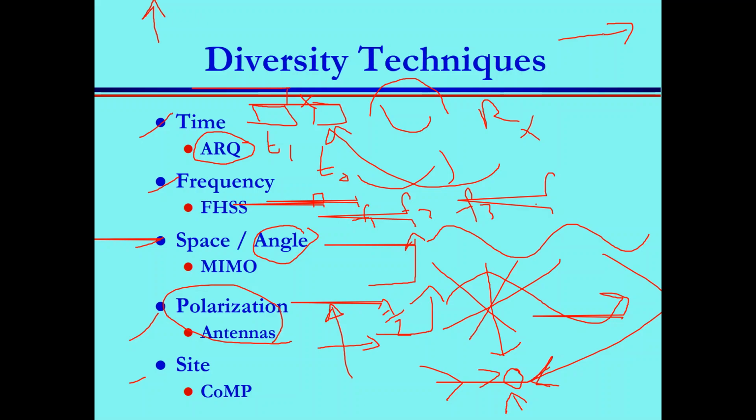Otherwise, you cannot induce current. It has to be aligned. Now, in millimeter wave, this is a problem. If your transmitter and receiver don't have the same polarization, you might not receive your signal, although your signal is reaching the receiver, and you might get confused. There is signal, but I'm not receiving my data. Why? Because of the polarization.